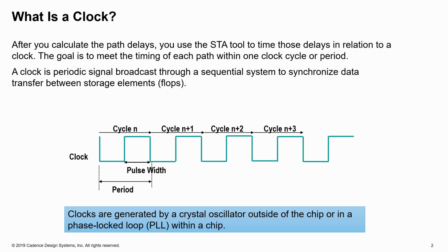When you see posedge clock, that triggers the creation of a positive edge flop. And negedge clock triggers the creation of negative edge triggered flops, and latches are created via the always @(clock) constructs.